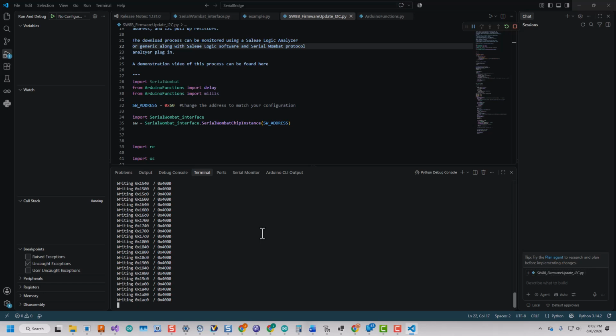You can see that it runs a little bit slower here compared to other versions because the bridge adds extra latency as it gets the packet over UART, sends it out over I2C, gets it back, then sends it back over the UART.